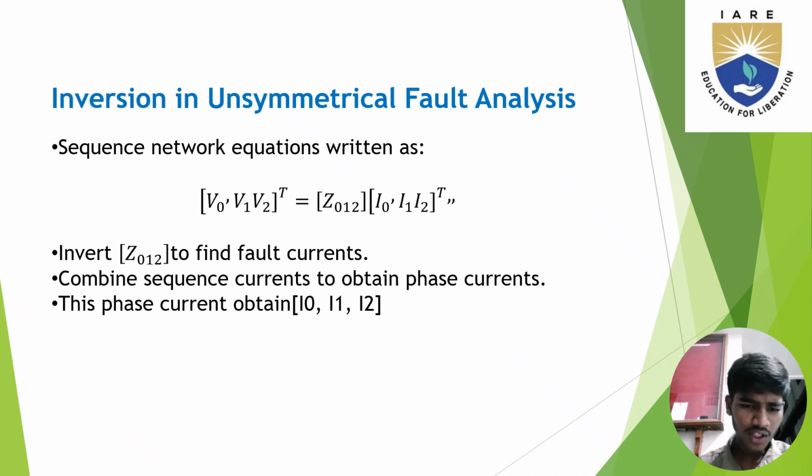Now invert Z012 to find the fault currents. Combine the sequence currents to obtain the phase currents from I0, I1, I2.